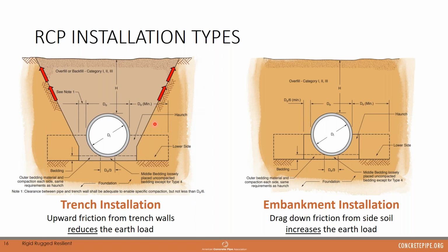Now, I guess the practical side of that is it's very difficult to control trench width in the field. It's hard to know. I mean, some contractors, no matter how well intended they are, for one reason or another, they may have to open up the excavation much wider than you specify. So you have to really be mindful of that.